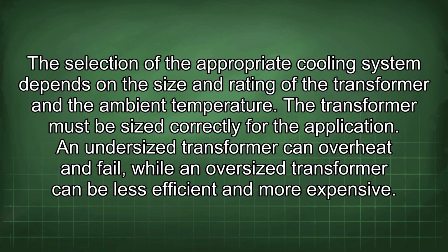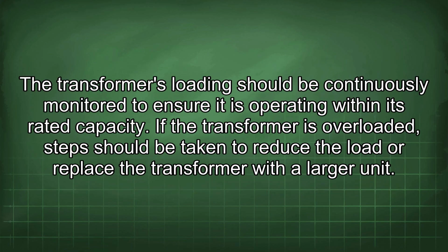The transformer must be sized correctly for the application. An undersized transformer can overheat and fail, while an oversized transformer can be less efficient and more expensive. The transformer's loading should be continuously monitored to ensure it is operating within its rated capacity. If the transformer is overloaded, steps should be taken to reduce the load or replace the transformer with a larger unit.